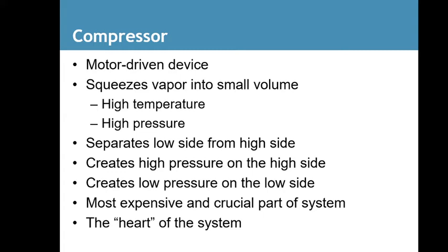Compressors are motor-driven items. They don't do their job without a motor built inside of the normal residential unit. They're hermetic devices, so the motor is sealed inside the unit. The compressor squeezes vapor into a small volume. High temperature, high pressure is what it turns the low pressure, low temperature vapor into.